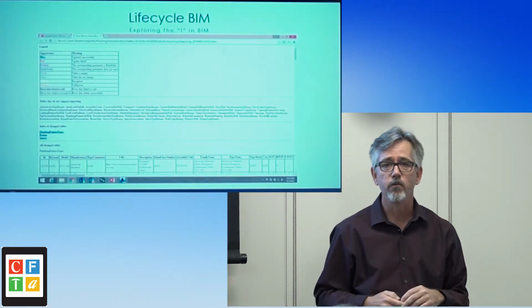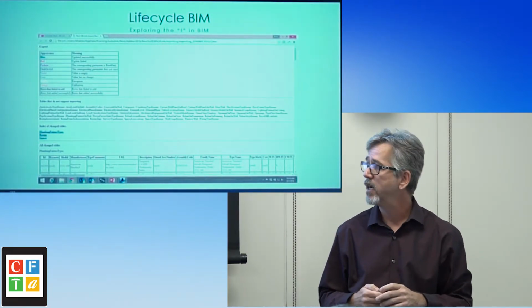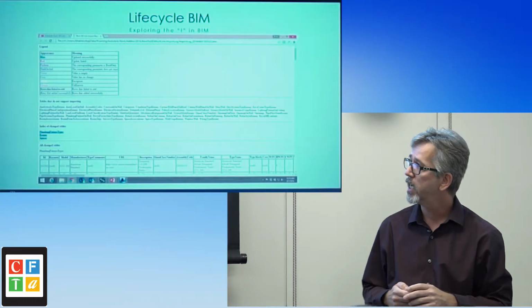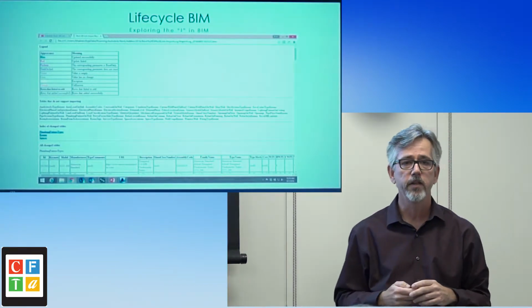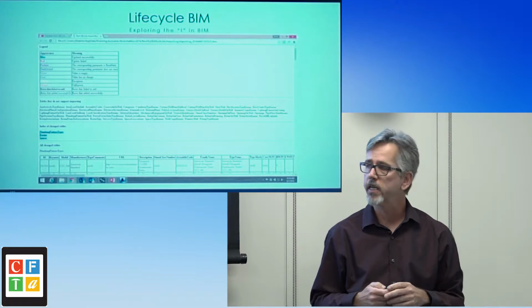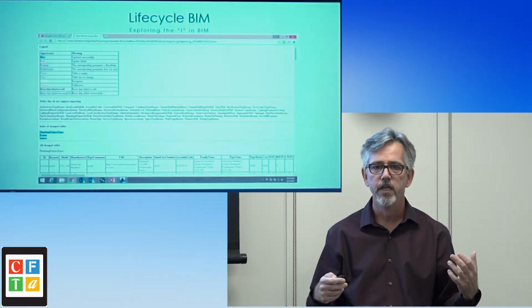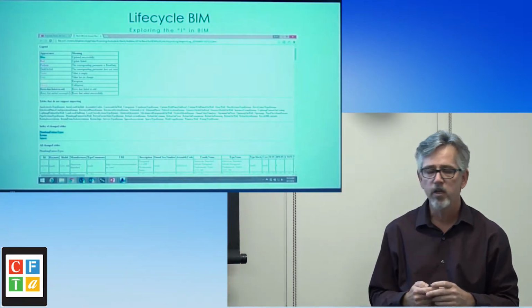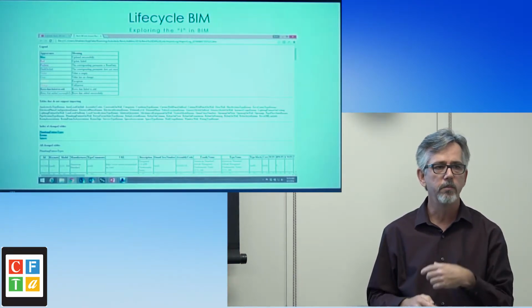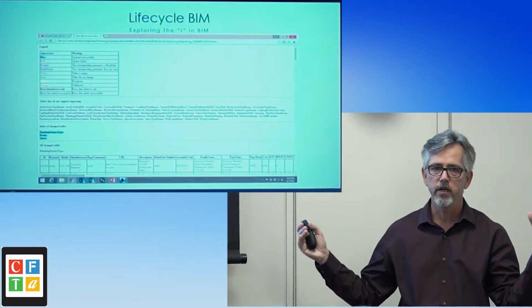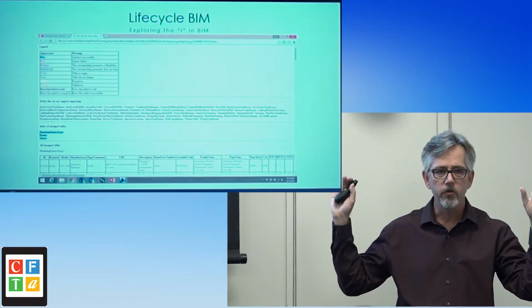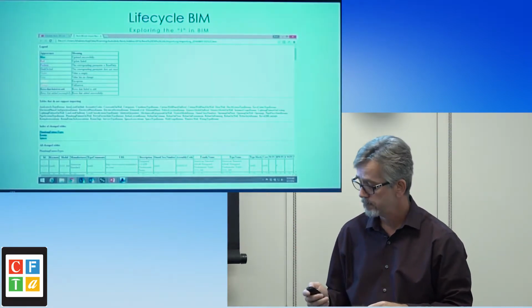The last thing it does is run an audit. It's kind of nice, and it will tell you everything that changed, kind of give you a little bit of a report. It will tell you the data values that changed, what was filled in, et cetera. So it's a nice little tool. If you ever want to explore the information that's in a model and you've been a little bit nervous about doing that, you can run this on a model. It will kick out everything. Doors, windows, you name it. It kicks out everything into the spreadsheet.